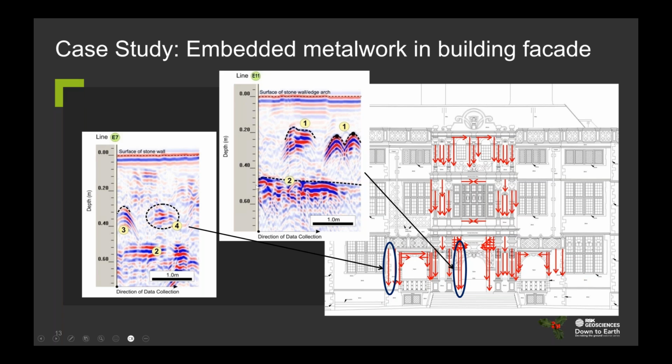The depth that's shown on the side of any of these ground penetrating radar depth slices, cross sections, generally will have either been approximated based on a known velocity for the material that we understand we're surveying over, or through calibration from known depths to metalwork.